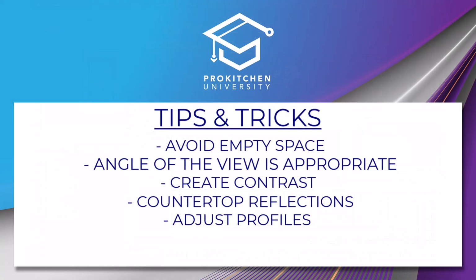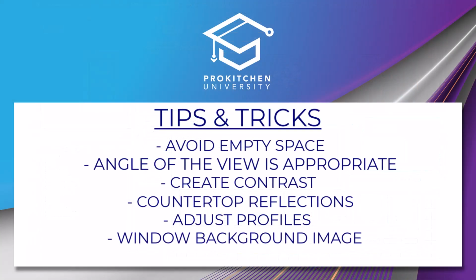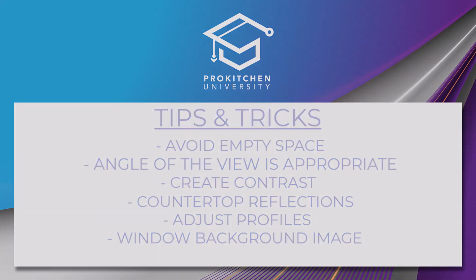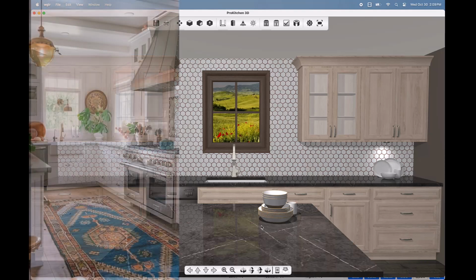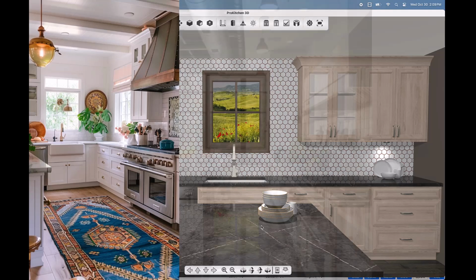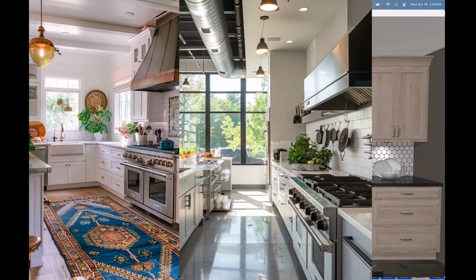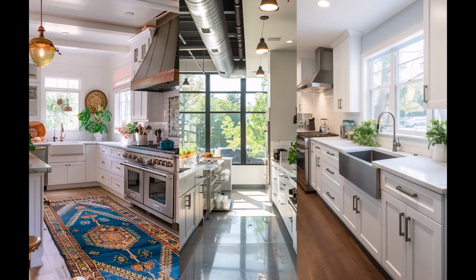Another item to be aware of is the window or glass door background image. Using high-quality digital images for the backgrounds of windows and glass doors is strongly suggested. However, at full saturation, these may look not as natural and a little out of place within the 3D rendering. When we look at the images of real-life kitchens, due to the natural refraction of light, the view from a window is less saturated in color.